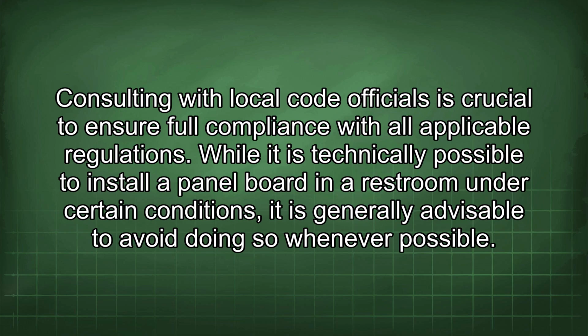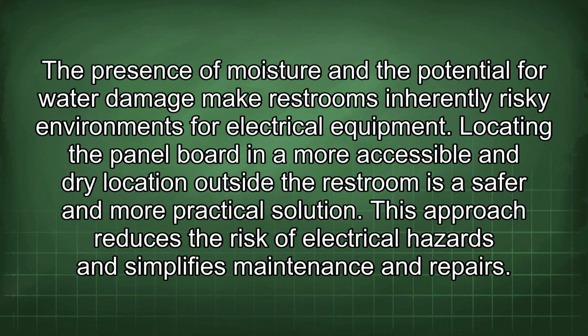While it is technically possible to install a panel board in a restroom under certain conditions, it is generally advisable to avoid doing so whenever possible. The presence of moisture and the potential for water damage make restrooms inherently risky environments for electrical equipment. Locating the panel board in a more accessible and dry location outside the restroom is a safer and more practical solution. This approach reduces the risk of electrical hazards and simplifies maintenance and repairs.